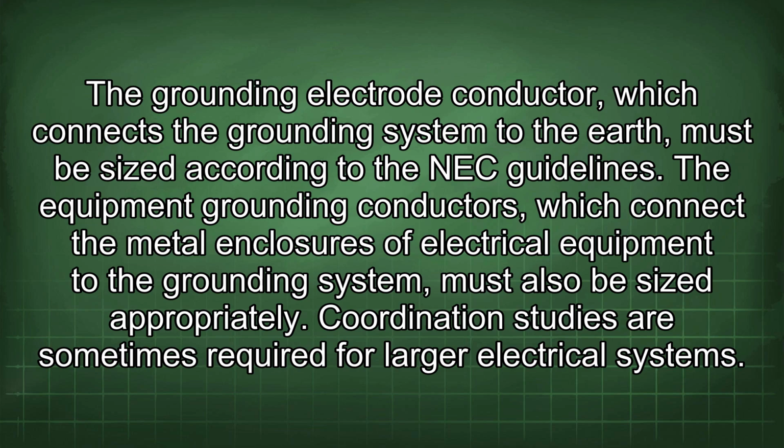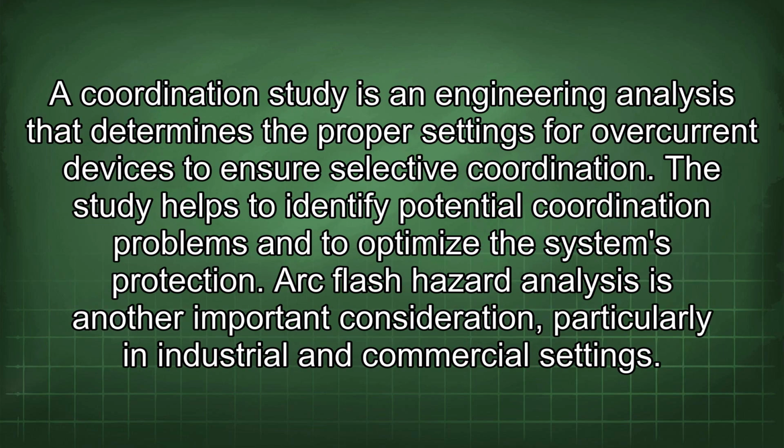Coordination studies are sometimes required for larger electrical systems. A coordination study is an engineering analysis that determines the proper settings for overcurrent devices to ensure selective coordination. The study helps to identify potential coordination problems and to optimize the system's protection.